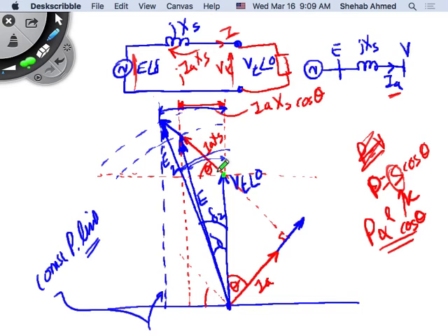I ignored the resistance here. But this armature current will have a maximum value, meaning this voltage drop inside the generator should be a maximum value. Otherwise, all this heat inside the generator will raise its temperature to a limit I cannot control. So there is a limit due to maximum armature current that I can draw around this radius here.